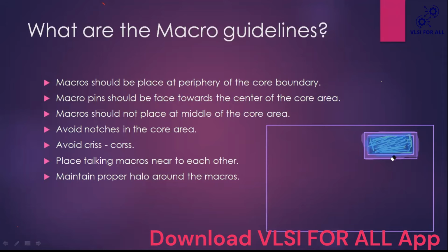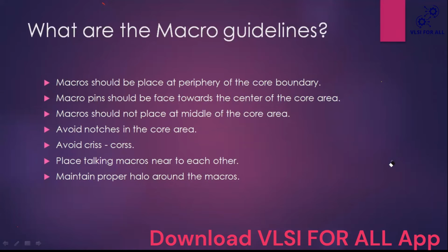They need some tracks, and standard cells also need some tracks. So there may be more congestion at those places. These are the major guidelines we should follow while placing macros.